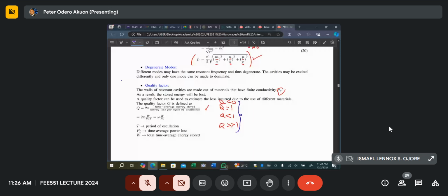To have a very high Q, compared to if we were to use an RLC circuit that would radiate. At high frequency, there will be a very small skin depth, so most of the energy will be flowing at the surface, where we lose it due to radiation in an RLC circuit. So that's why we use this cavity.